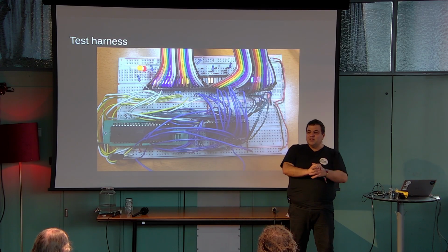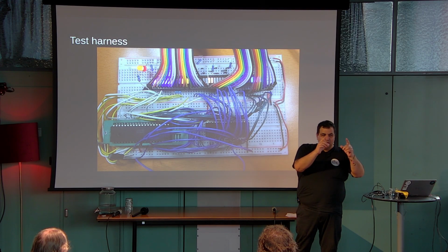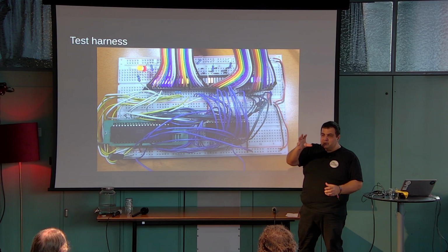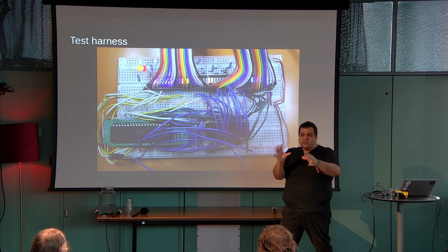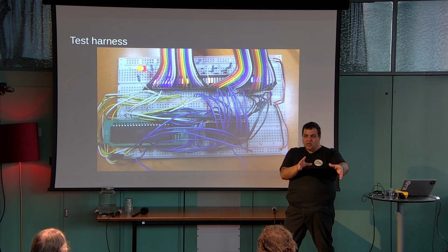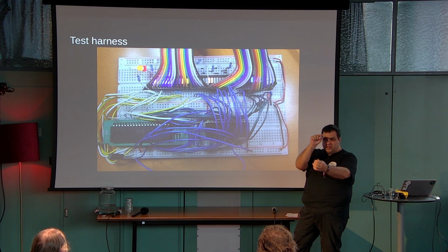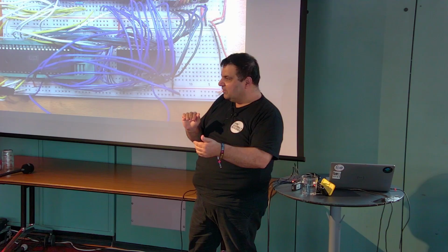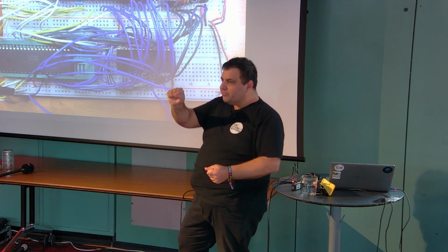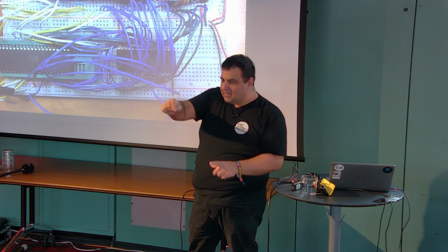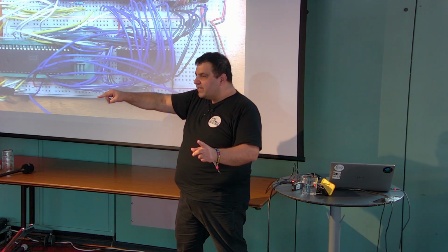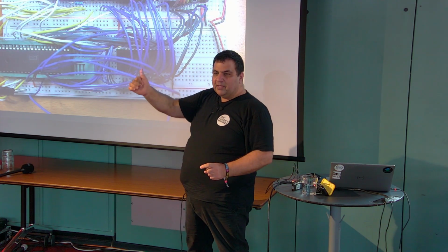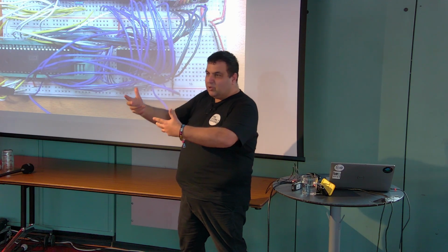And then comes the interesting part. You do the same thing. This Python program can do I/O. So you have a memory area where if you write to it, the test is done. Or you have a memory area where if you write a number to it, that many cycles later the interrupt signal will go low, will go active.